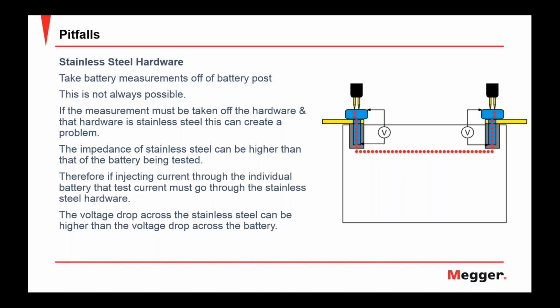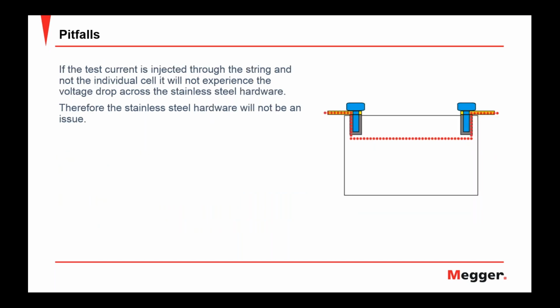If I have a system that is injecting current through the entire string, then I'm not having to deal with that hardware. It goes actually right through from the strap to the terminal, right through the battery. So I will be able to actually get better measurements with that.